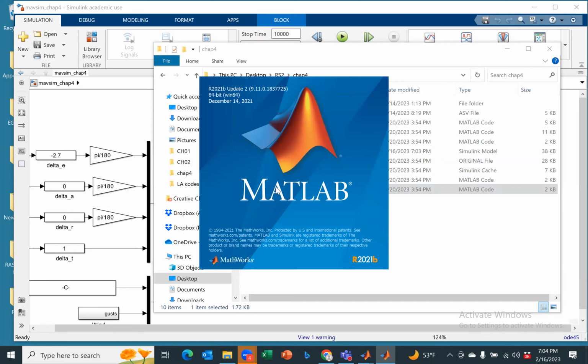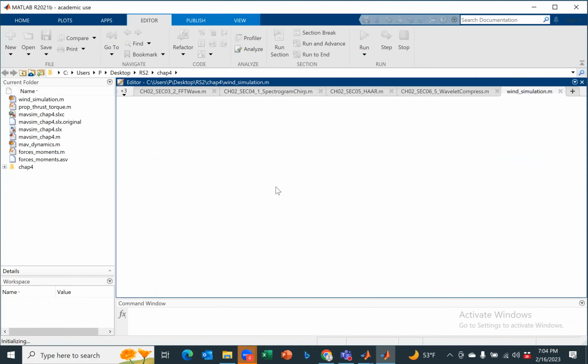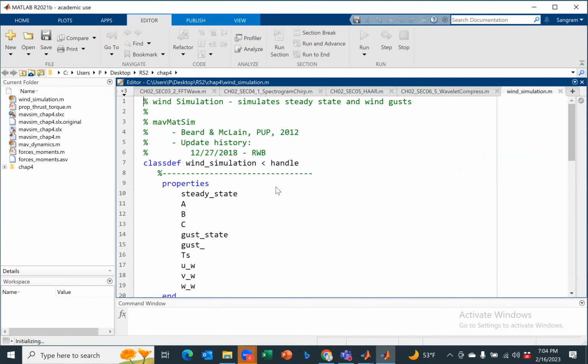Yeah, that's sufficient. And if you want to take a shortcut, what you can do is you can go to MATLAB aerospace blockset, wind, and there is actually a wind model that you can grab. It will do the exact same thing. Okay, so this is the wind simulation.